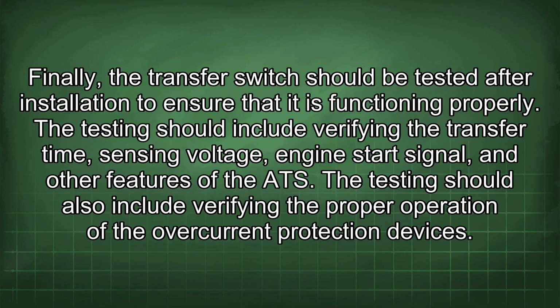Finally, the transfer switch should be tested after installation to ensure that it is functioning properly. The testing should include verifying the transfer time, sensing voltage, engine start signal, and other features of the ATS. The testing should also include verifying the proper operation of the overcurrent protection devices.